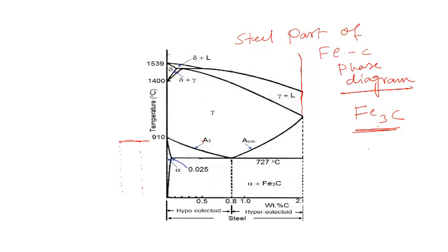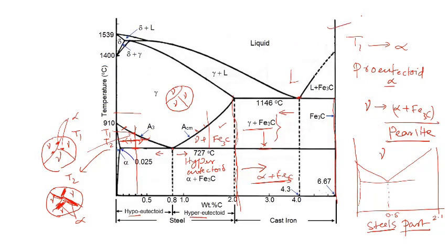If you have a phase diagram between A and B, we know that the phase diagram terminates at B, right. When you see the composition in terms of percent B, then at the right hand side it terminates at 100% B, right. So here also, if you go back to this, it is terminating at the cementite line. So cementite is like a component here rather than a phase.